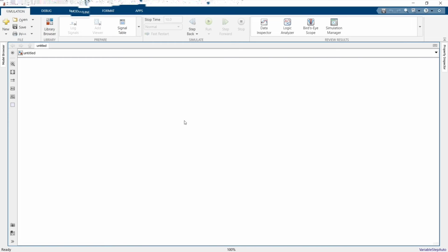I'll again provide the values to the PID: 0.75, then 50, and 3.2e-6. I'll go to saturation and I'll limit the output to 0.9. Since I have copied it, these values are there. So this is my constant current charging scheme or method.